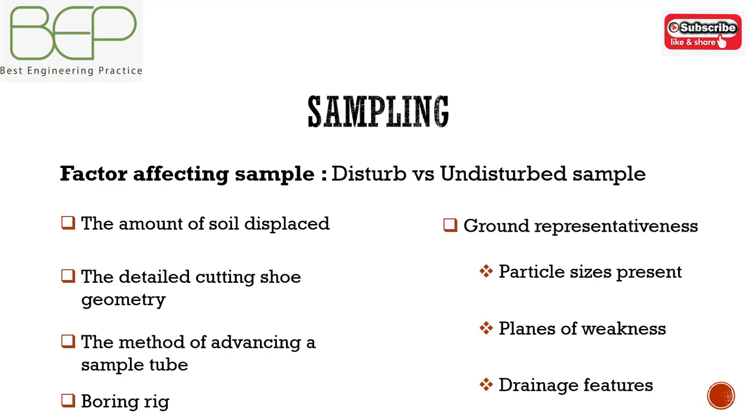In addition, they must not be damaged during transportation to the laboratory, and they must not be allowed to dry out during storage. All samples should be carefully sealed as soon as they are brought to the surface to prevent moisture loss.